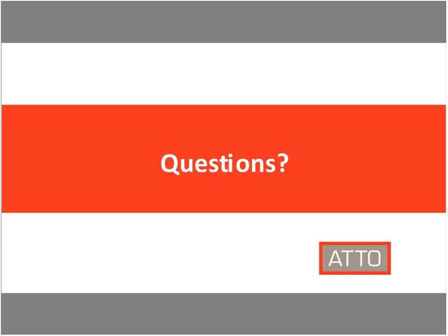That's a good question as well. Some of the hosts that I listed in the presentation have been tested by ATTO already for compatibility and for maximum throughput. You can also check out the atto.com website. We have an interoperability matrix that will also point to the hosts that ATTO has tested with. But one of the things I do want to point out is that it's important for users to verify that the Thunderbolt port was fully routed on a host when they purchase it, because some of them were only routed for half of the lanes. Anything that ATTO lists on our interoperability site has been tested for full throughput, but you want to double check before purchasing a host that you're able to get your max throughput of Thunderbolt 3.